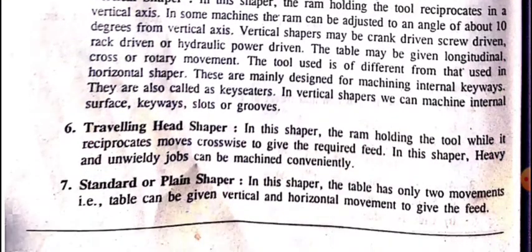So next comes traveling head shaper. What is this traveling head shaper? In this shaper, the ram holding the tool reciprocates and moves crosswise to give the required feed. Heavy and unwieldy jobs can be machined conveniently in this traveling head shaper.